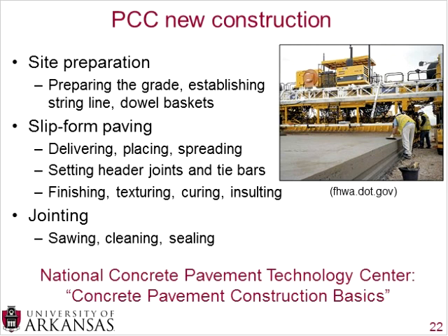You can have the best materials in the world, the best mix design in the world, and the best construction in the world, but if it doesn't cure correctly, your pavement will not perform as it should. And finally, after the pavement has been placed and is cured, you need to joint it. Often you go in there with a saw in order to saw a joint that will force the crack and joint to occur at that location.